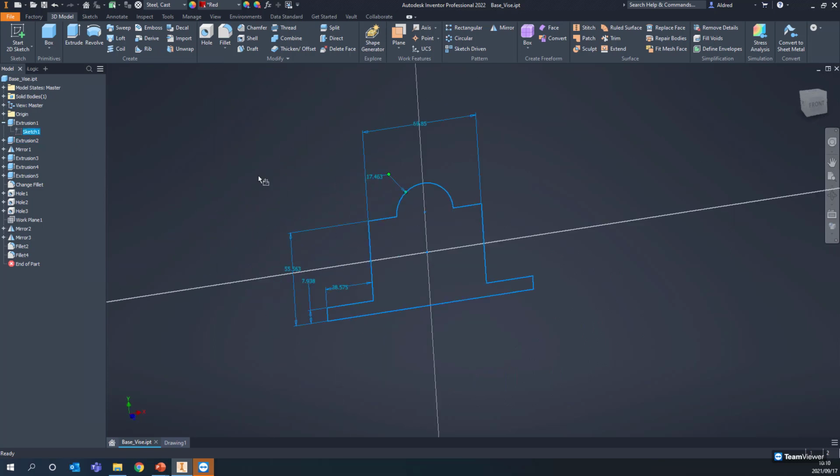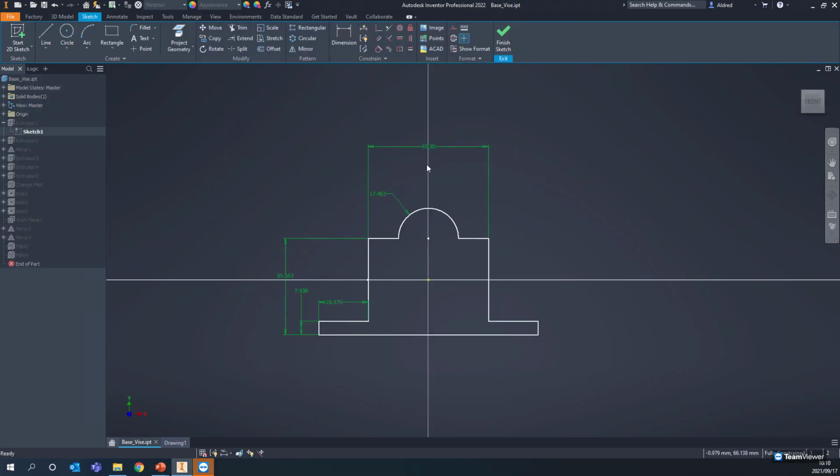renaming your different parameters. So if I take a look at this radius over here, you'll see the edit dimension is D2. Now, as I said, if you're going to take a look at D2, what is that? What does it pertain to? If I change it, what else is going to change? You don't really know. So from the get-go, if you want to, you could name it rad1 or equals. So maybe I've got a legend somewhere that says rad1 is the top curve of this vice.